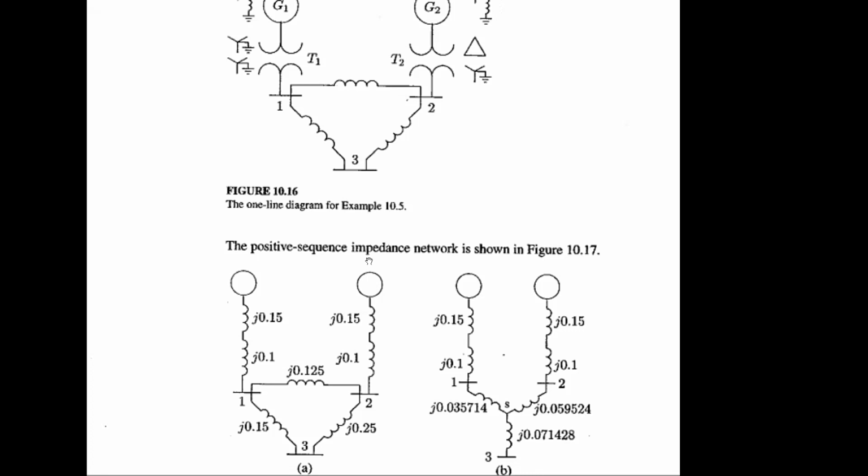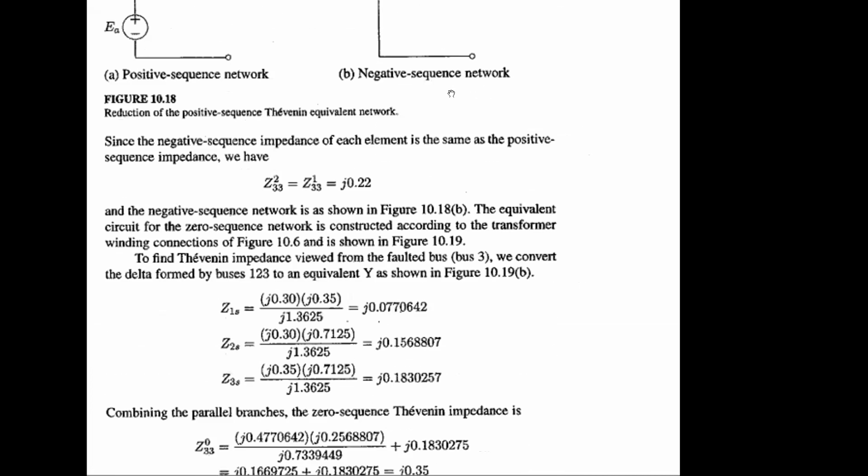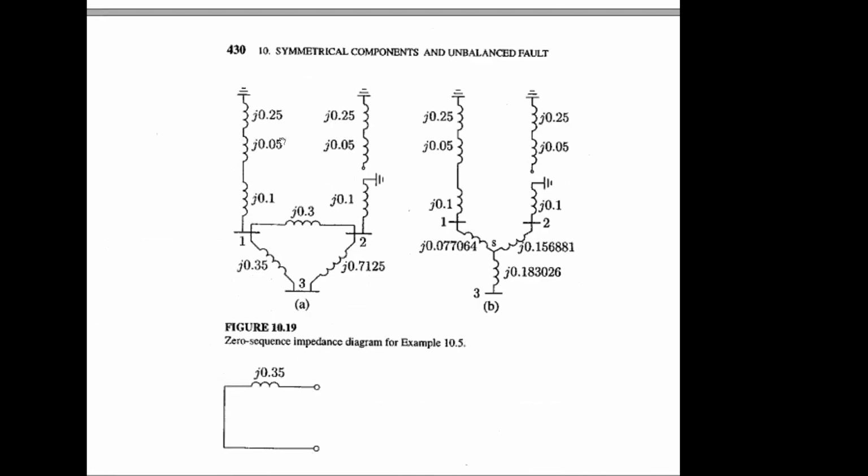If you specify that, it will be only the positive sequence impedance. So you can easily draw the positive sequence impedance without considering the transformer internal scenario. But when you want to address the transformer zero sequence circuit like this one, the transformer internal circuit, in this part there is a delta, and you have to consider that. So for the zero sequence transformer equivalent circuit, you have to be very careful.